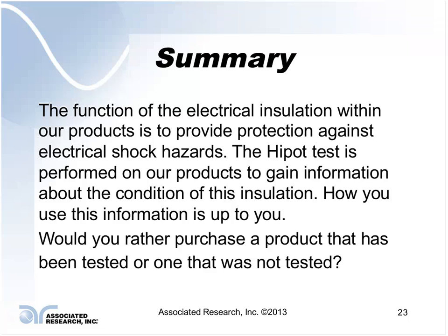So if you're trying to apply your test potential instantaneously, doing a 1-second test, that meter never settles in on a value before the test is over. So yeah, ramping can tell you, if a failure does occur, at what potential it actually failed. It may help you in predicting whether an item is going to fail or not.